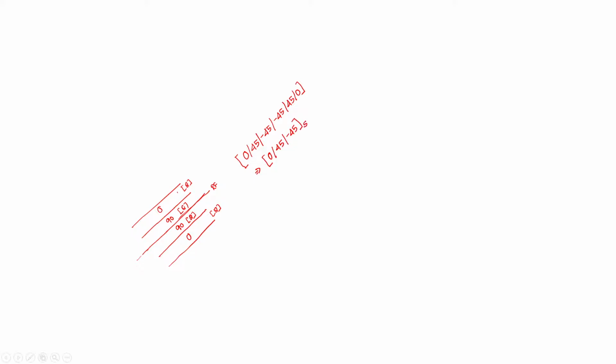Now cross-ply symmetric means the layers will be only 0 and 90. This is called cross-ply symmetric laminate. Sometimes also called specially orthotropic symmetric laminate, because all the layers are either 0 or 90.